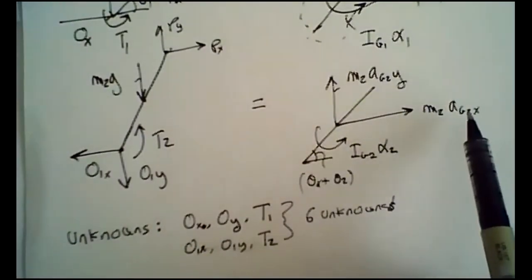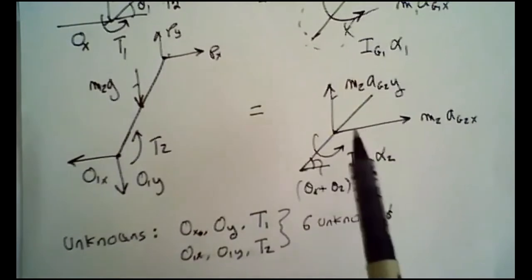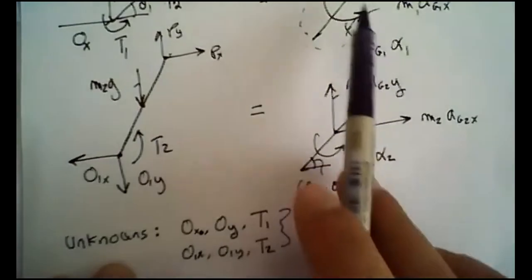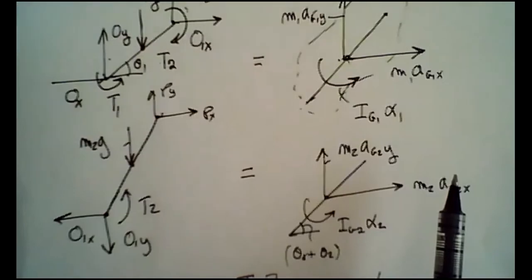Obviously, we're going to assume that we know AG2. We know all of these on the right side, in the inertial accelerations and inertial forces. Okay, let's now find AG1x, AG1y. We have two techniques. One we learned in our dynamics course, which is based on vector dynamics. Another one, which I'm going to introduce here, is simply based on differentiating the position.